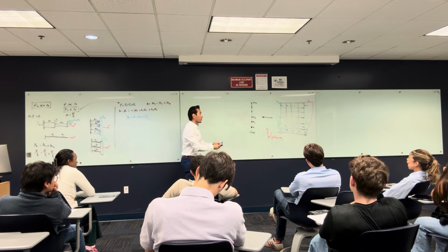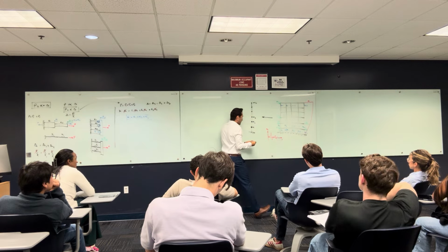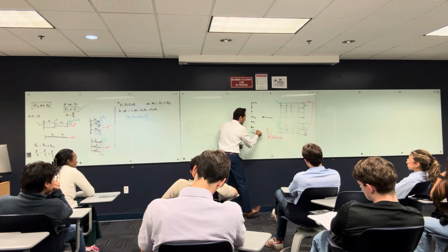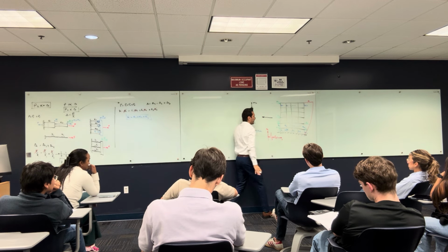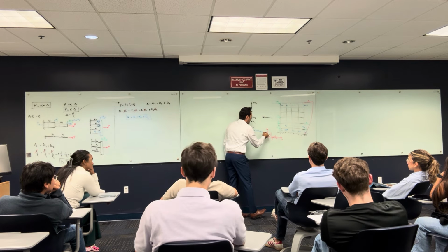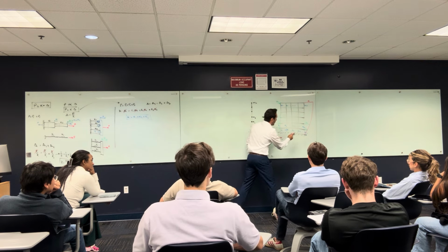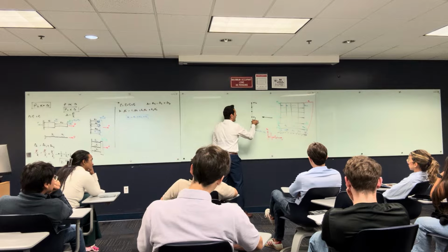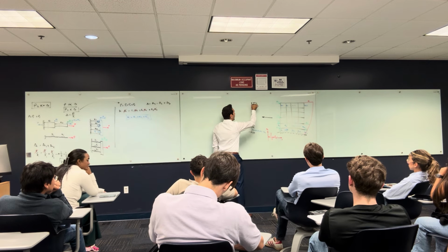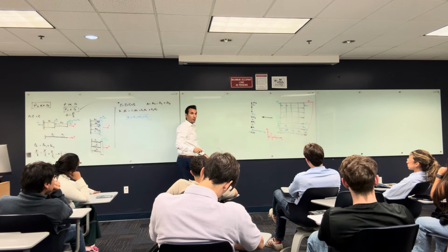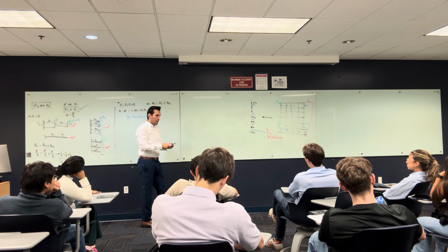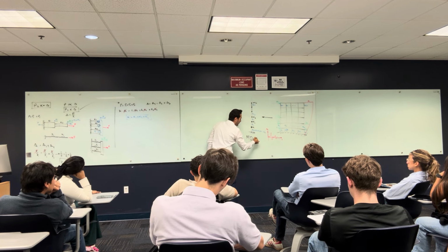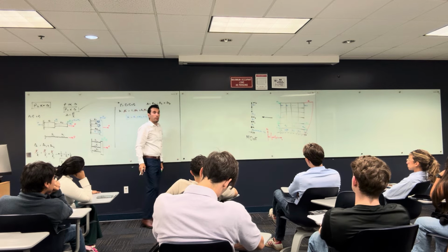All right. So the thing is, I can get the K equivalent of story number 1, K1, and K1 is equal to K plus K plus K. Let's say all the columns have the same amount of K, whatever K, in story number 1. So this is going to have K2, K3, K4, until Kn. So every story has a different stiffness. That is the first simplification, and this simplification is called multi-degree of freedom system, MDOF.